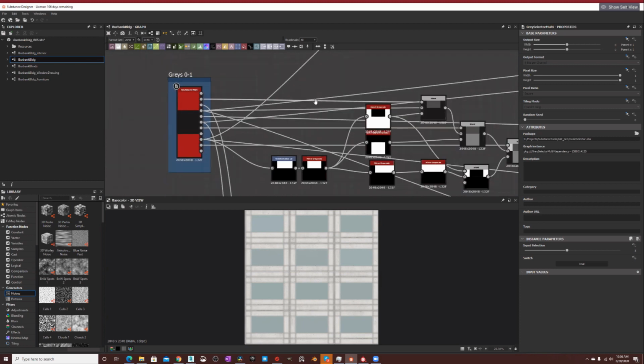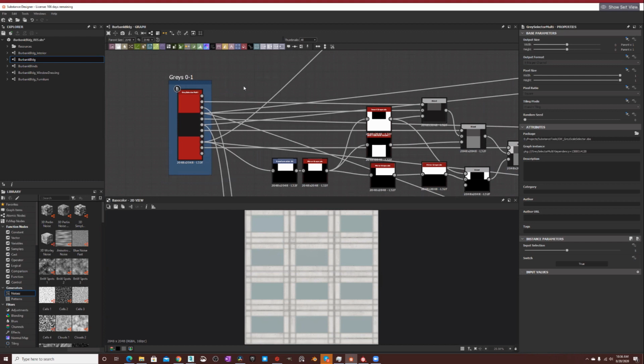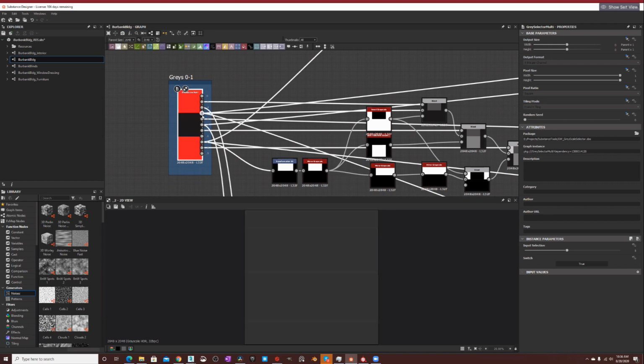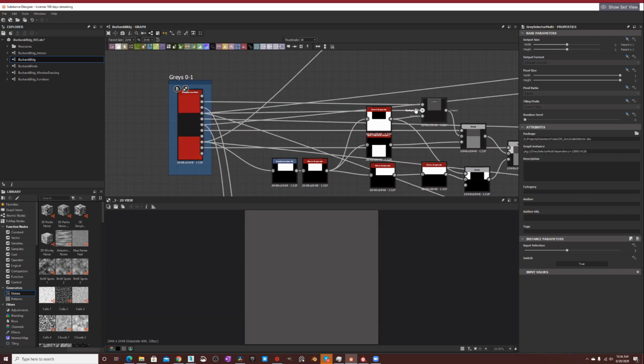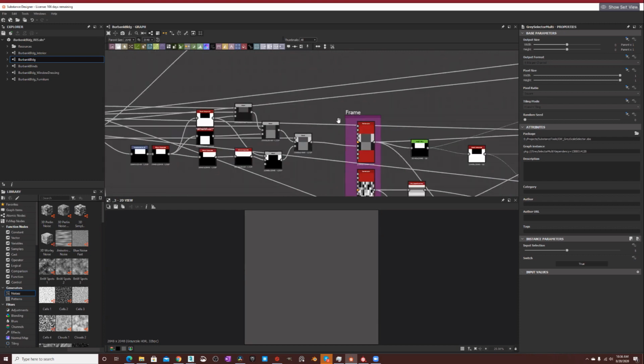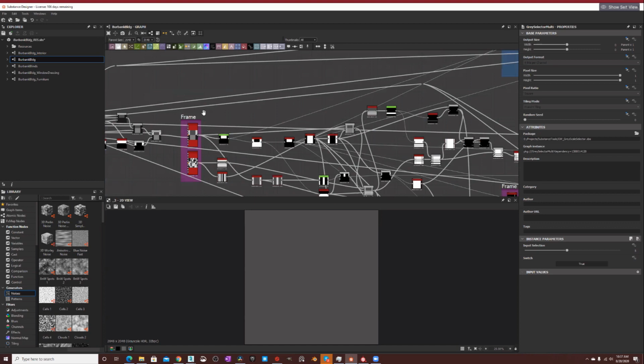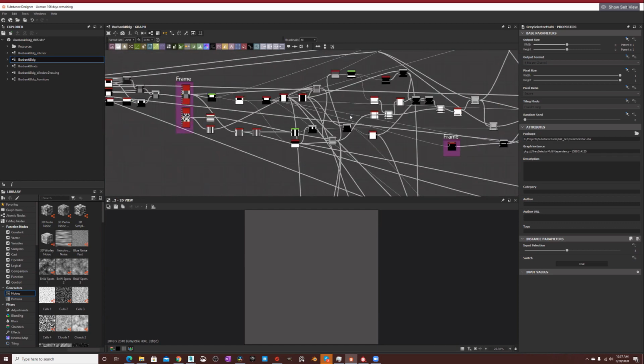Before this, I would choose colors. When you're making your height map in Substance Designer, you tend to choose grays kind of arbitrarily, so I created this tool. It's just grays 0 to 1. So it's obviously 0, 0.1, 0.2, 0.3. That is a simple tool. And that meant that anytime I was choosing colors, I was always able to select them later on within the graph.